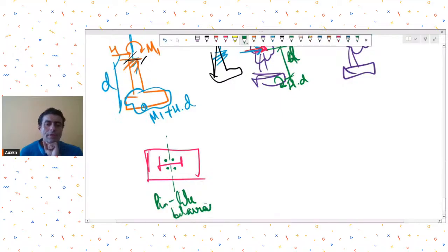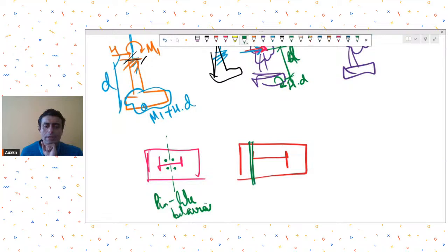It's not an exact pin behavior, but pin-like behavior. For I-section columns, if you want to come up with a fixed support or a moment rigid joint, then you have to place, let's say, these gussets, and then you may have to provide bolts.